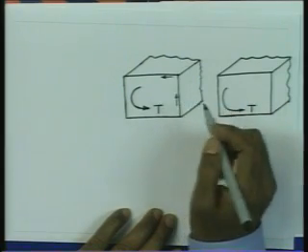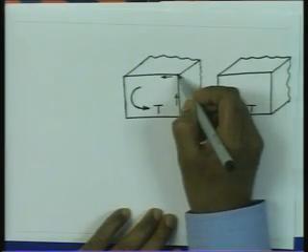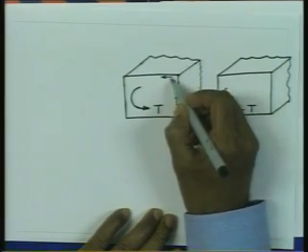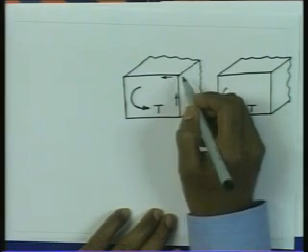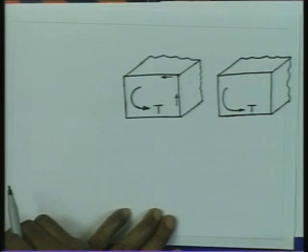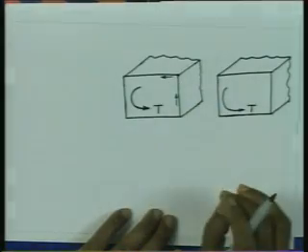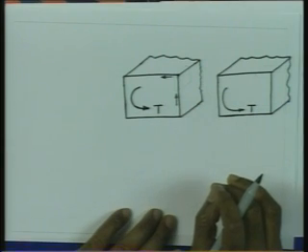close to this boundary. Now, at the corner, which is a common point, it has therefore possibility of stress acting in this direction and also in this direction. It is a single point and it cannot have two directions of the shear stress acting, and therefore from the uniqueness of the stress, the possibility is that this stress has got to be 0, both the stresses are going to be 0. That is from the consideration of this uniqueness of the stress.